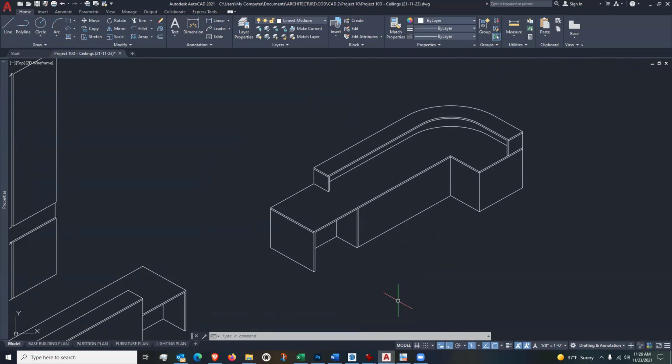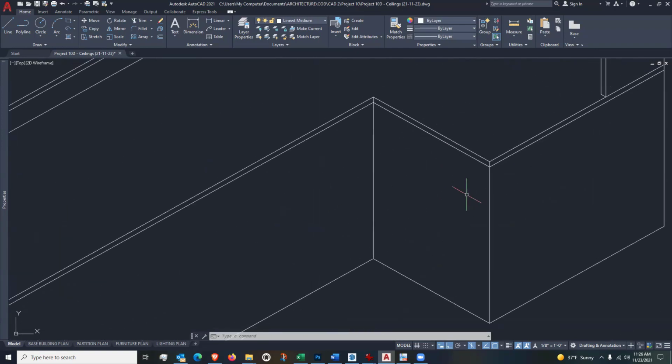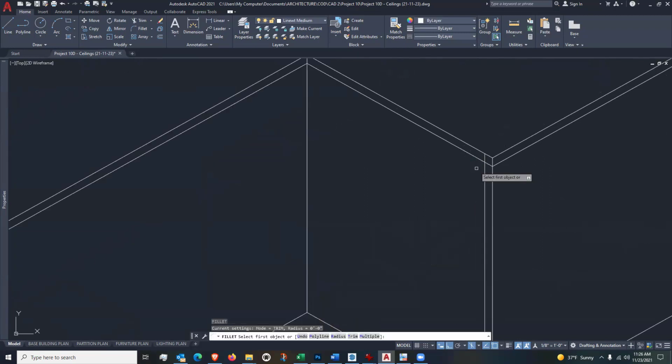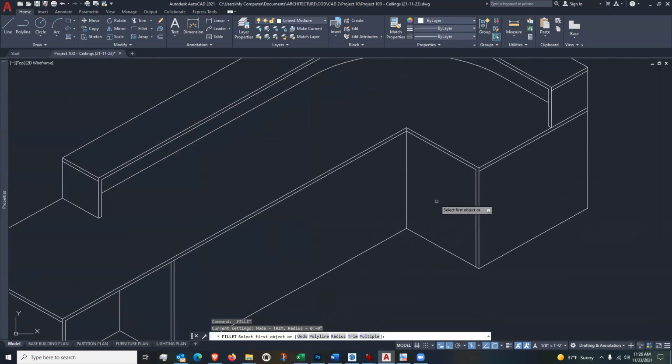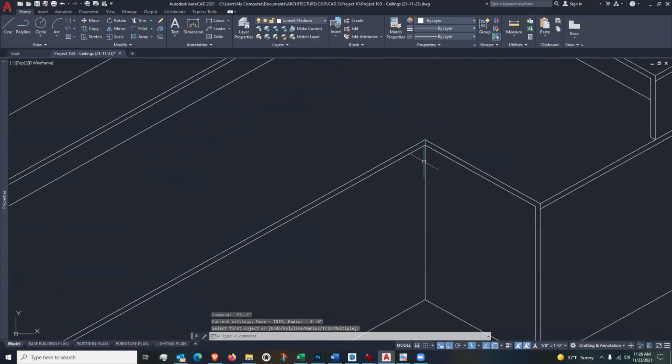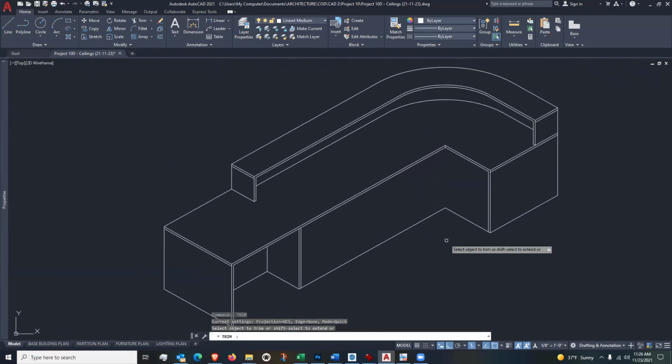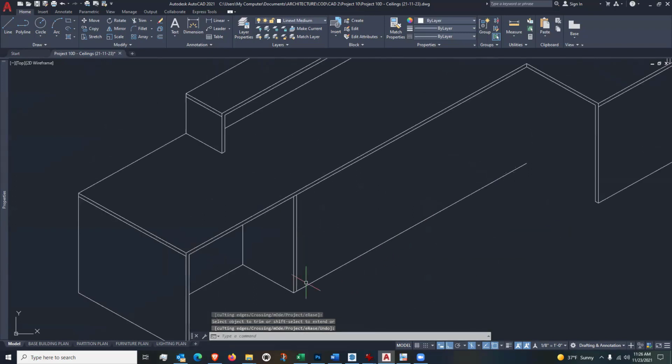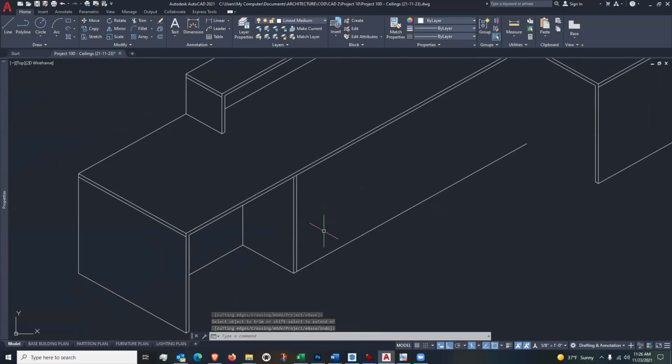All right, now, I need a leg here on this side. So I need to copy over 1 inch and then trim there or fillet. I'll use fillet for that. And I won't see this line, but so I'll trim down here. And I'll get rid of that for now. And then, so the last thing I've got are my PEDs here. So let me change to my isoplane right here.